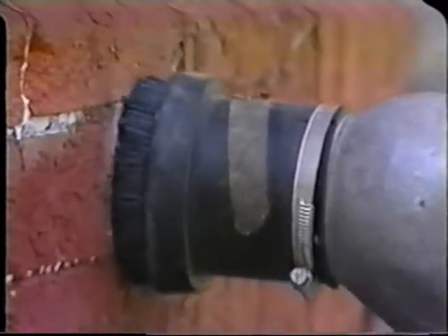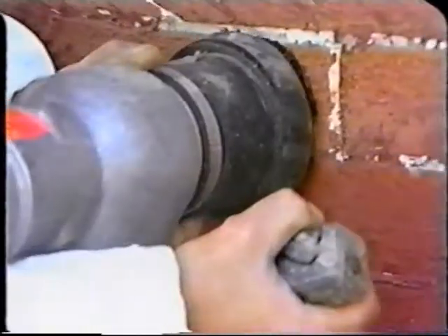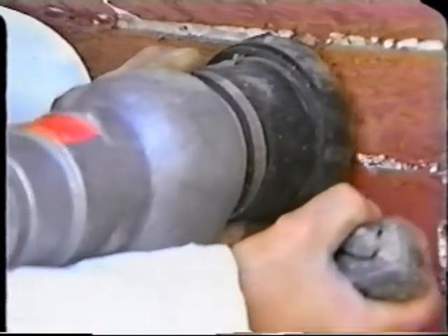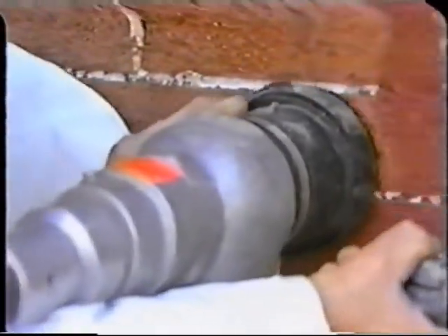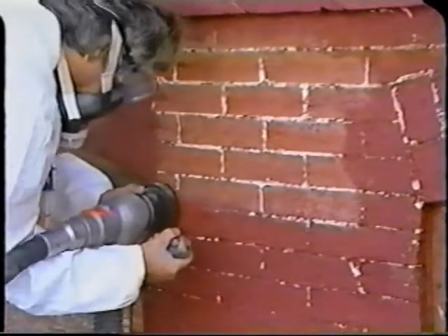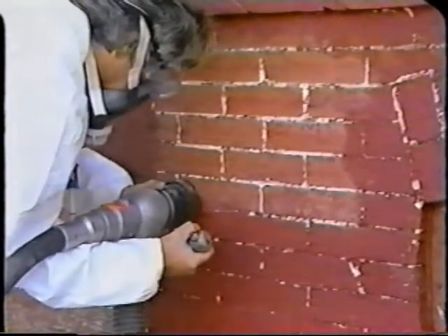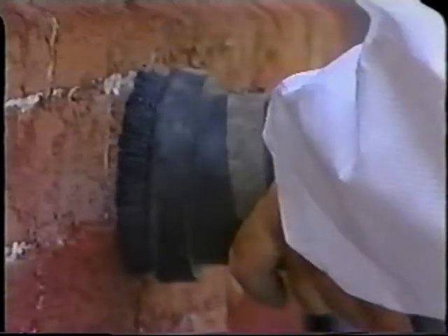Here, a vacuum blaster is shown as an effective and safe technique for exterior residential abatement use. The paint is blasted off with an abrasive. The dust is captured by the shroud and the vacuum. A choice of blasting media is available. Vacuum blasting is appropriate for metal, brick, concrete, and other hard surfaces. To be effective, the blast head must remain in continuous contact with the surface.